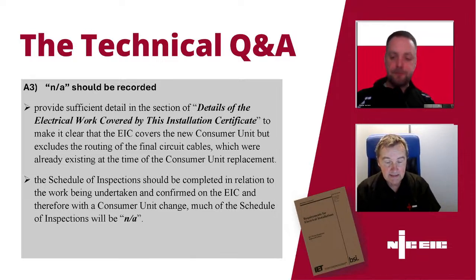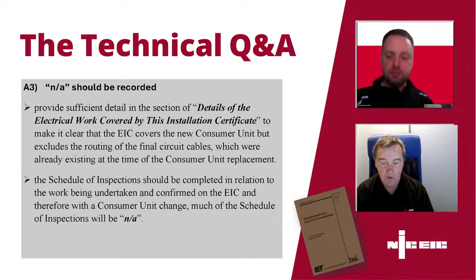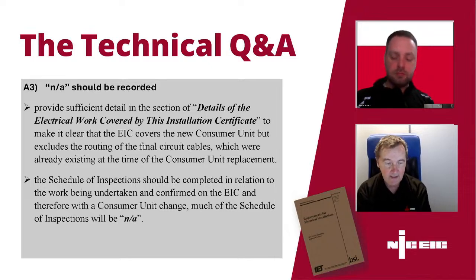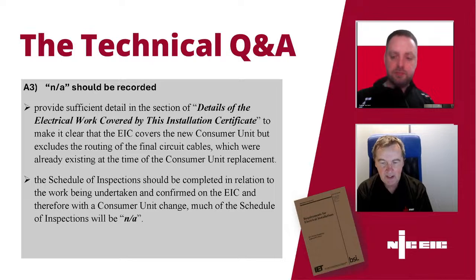So in this instance, it is just the board change and a reconnection of existing final circuits, which means you're not taking responsibility for the install of those circuits, and therefore it's perfectly acceptable to say that it's not applicable what the installation method is. So I think sometimes people feel that when they do a board change, they've got to take responsibility for the whole installation, and that's not the purpose.